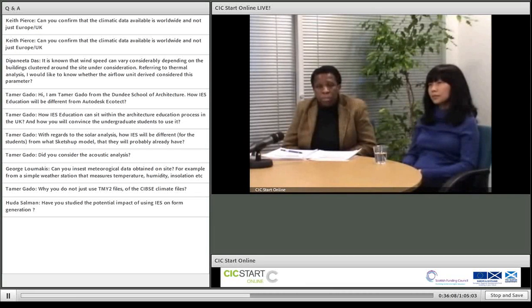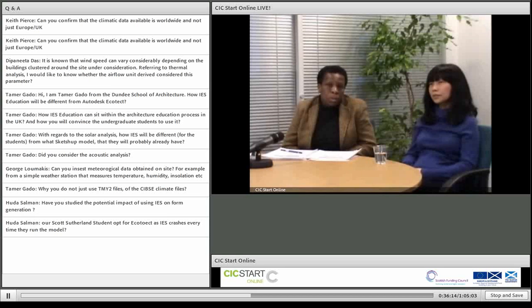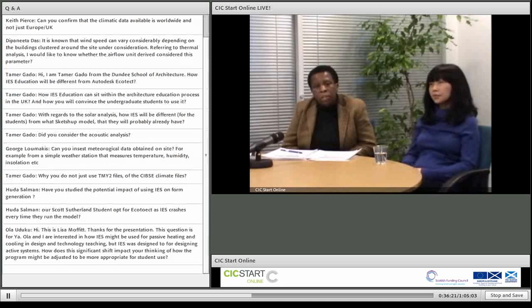So for example, your lighting analysis in, say, the Middle East is going to be very different from your lighting analysis in Iceland. So being able to use the climate files as well as the lighting situation, in terms of the ways in which the light goes through, gives you much more. And you're able to take a snapshot with the actual statistics and data there as well. So much as I say the visual is important, IES is a serious program as well. It will give you the statistics and data you need for your work.